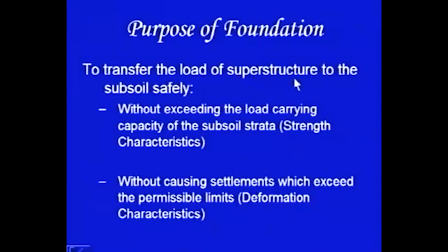When we say superstructure, it means the structure which you can see. The purpose of the foundation is to transfer this load from the superstructure to the subsoil. Subsoil means the ground which is under the foundation, and the purpose is to transfer this load safely. When we say safely, it means the load should not exceed the load carrying capacity of the subsoil strata. This is termed as strength characteristic. At the same time, there is a second requirement which we would like to confirm, and that is it should not cause settlements which exceed the permissible limits.